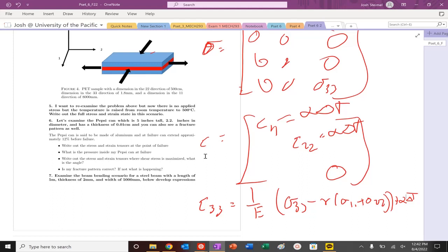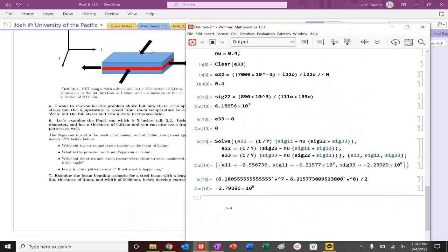Here we go. So, for example, for polymers, you can typically expect alpha to equal, let's say, 500 times 10 to the minus 6 inverse K. This is a relatively high thermal expansion coefficient.